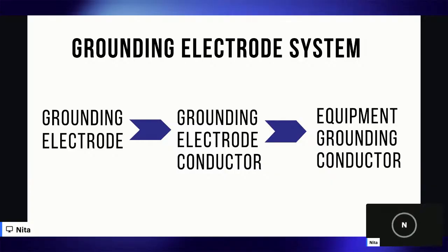We're safe. So when you look at your grounding bus bar, which is again a metal strip in your electrical panel, all of your equipment grounding conductors, those are those wires that we're looking at. Our EGCs terminate on the grounding bus bar in our main panel.